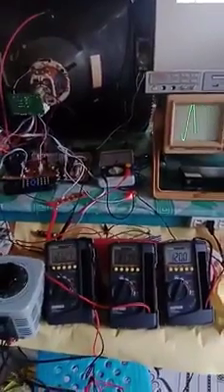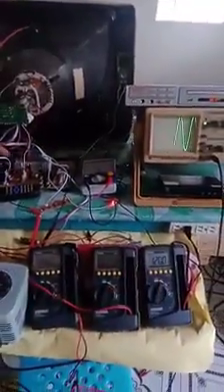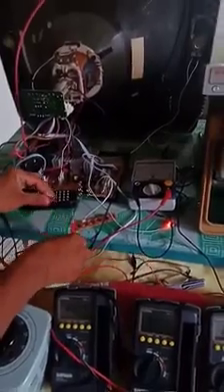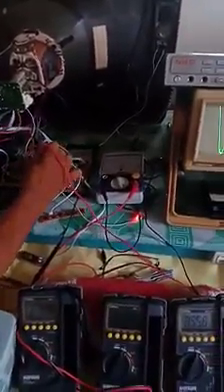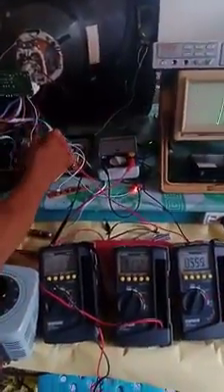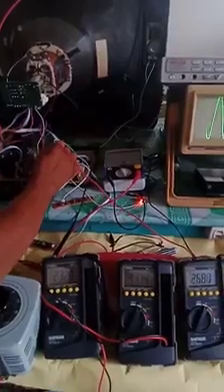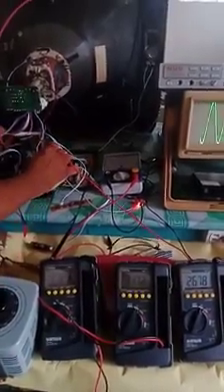So, the low voltage power supply is distributing 120 volts now towards the horizontal output transistor. So, it is not only 120 being provided to the circuits, but also there is voltage supplied to the vertical output IC. Look at this one. It is 26 volts provided by the low voltage power supply.